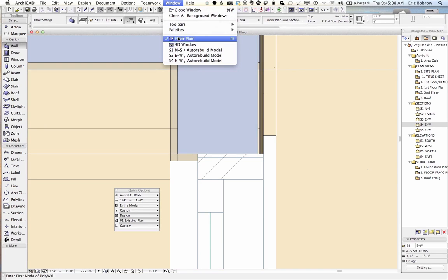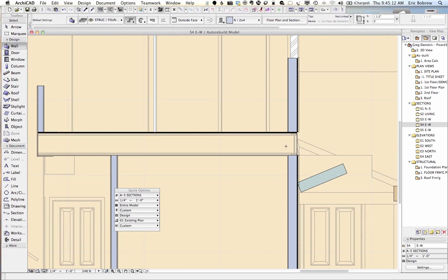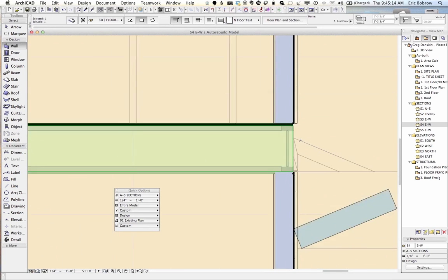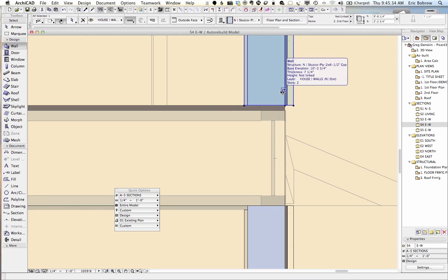Of course, I've got extra overlaps because I've got the original thing plus here you can see that the slab that I've just selected is going out to here, and we've also got the framing within that cavity there. And we'll need to do some solid element operations if we want to get the best result, but for now we can leave it.